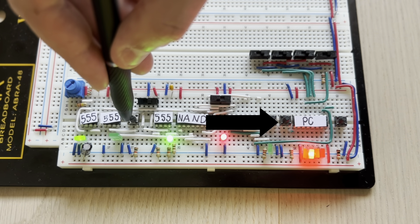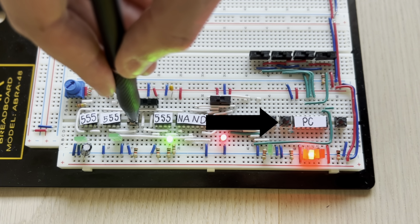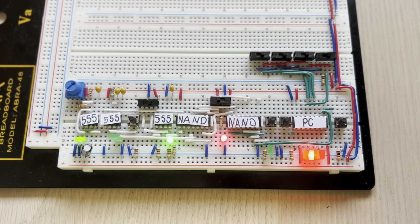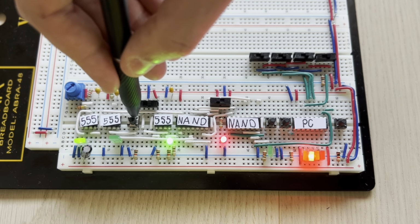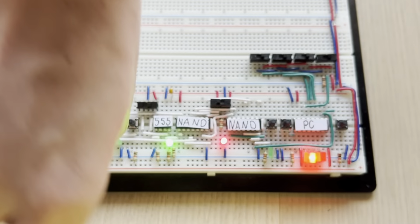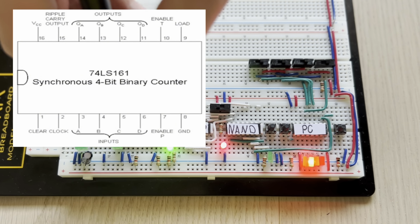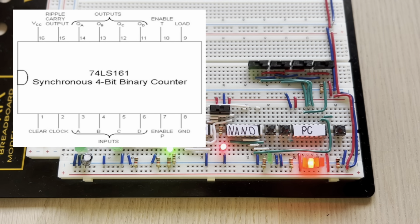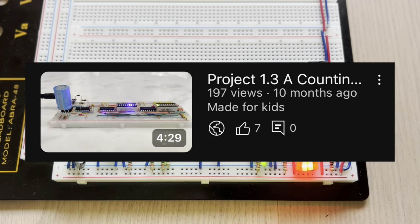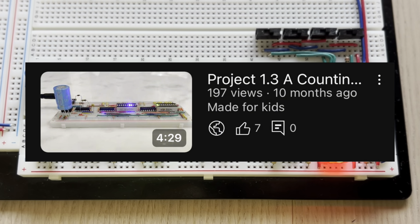Looking at the counter aspect of this specific project, the counter in a CHUMP computer increments the address and memory for each instruction cycle, keeping track of the next instruction to execute. It ensures the program runs sequentially unless a branch or jump occurs, as it is created through the use of a 74LS161AN chip, also known as a 4-bit synchronous binary counter. The chip is very similar to Project 1.3's decade counter, except has a few key differences.